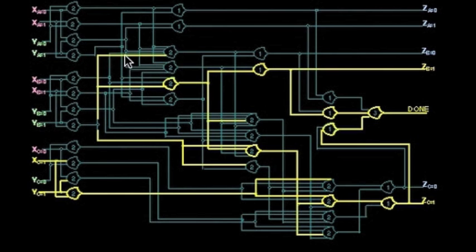But we can't determine that this path became null by observation, so we have to make a timing assumption. The timing assumption is that this wire path propagates strictly faster than it takes this path to propagate through logic, through the completeness, back, enable the input, and the next data wavefront to reach this branch node. And during design we can ensure that all the orphan paths are limited to a wire path, that they don't go through any gates. So we can make that a very valid assumption for most circuits.